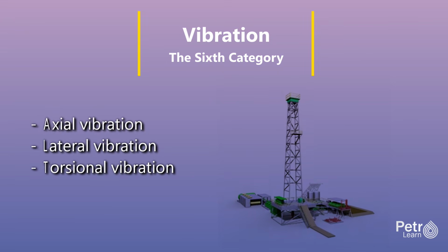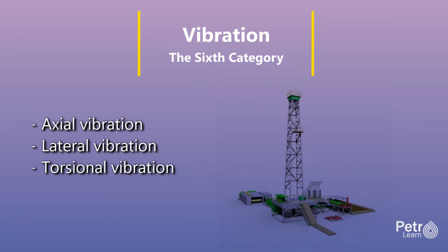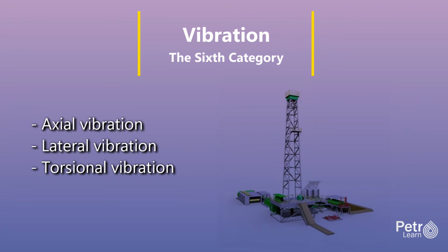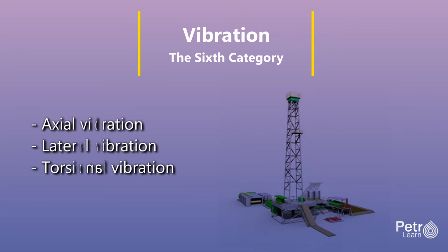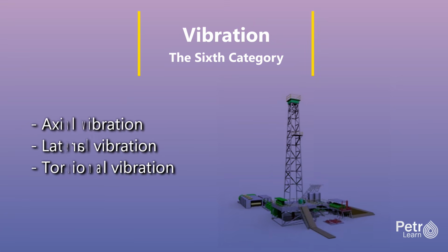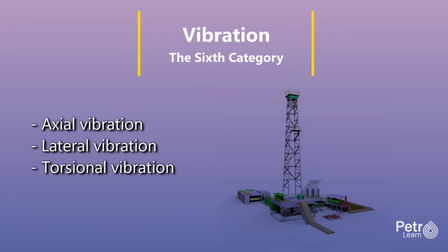The bit periodically stops rotating or slows dramatically while the drill string above continues to turn, storing torsional energy. When the bit breaks free, it accelerates to several times the average rotational speed. This cycle repeats many times per minute, creating extreme stress reversals that cause fatigue failures.